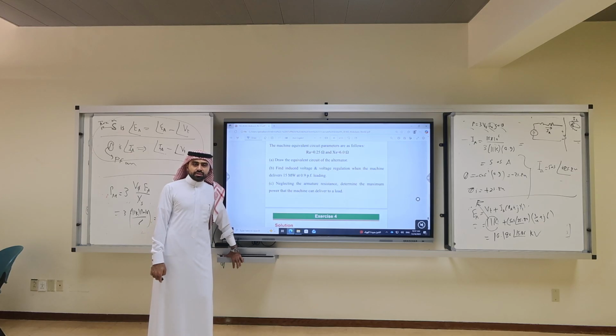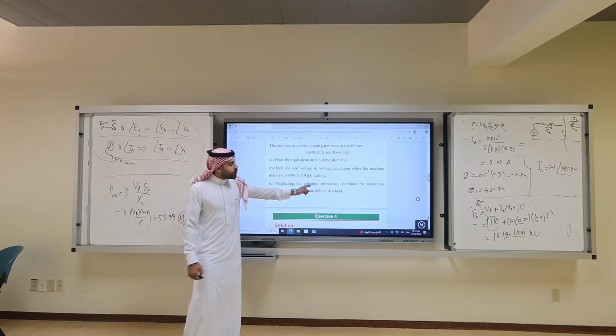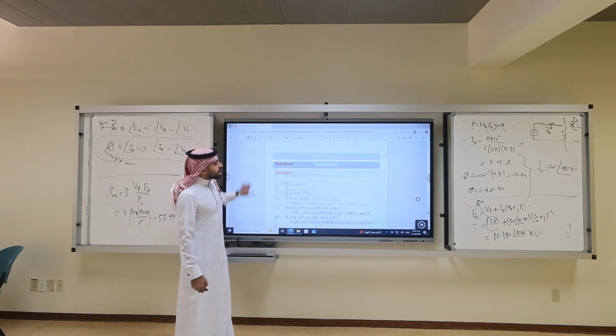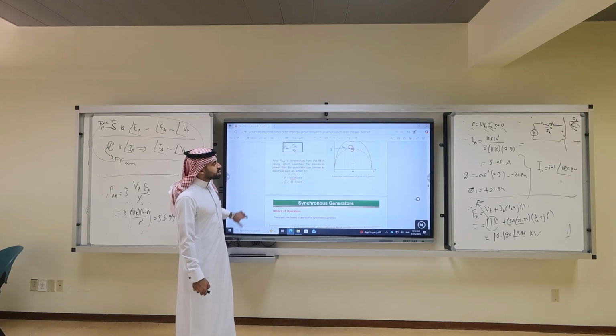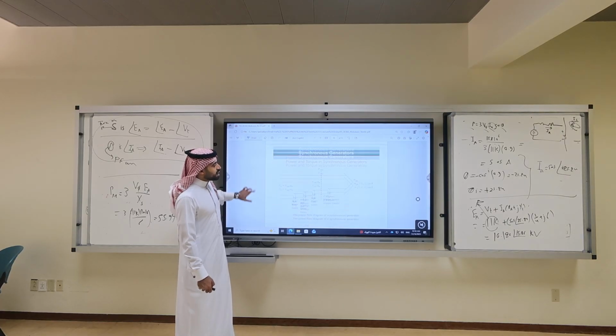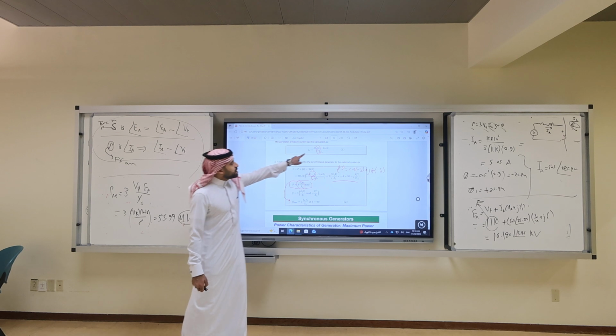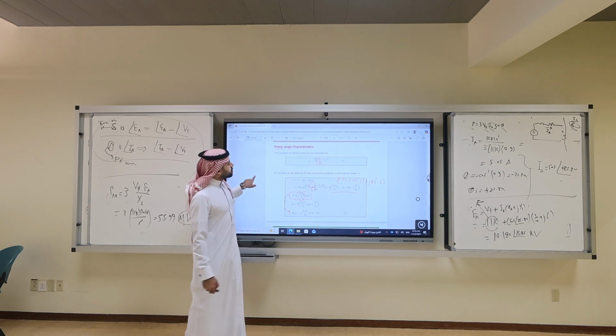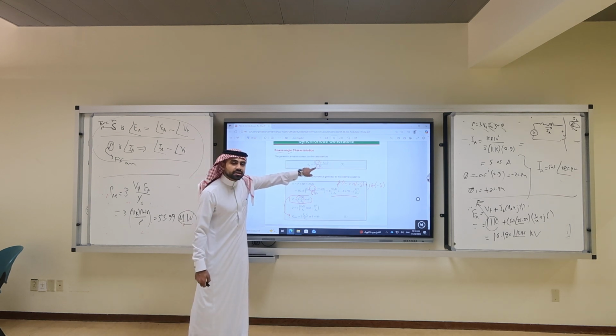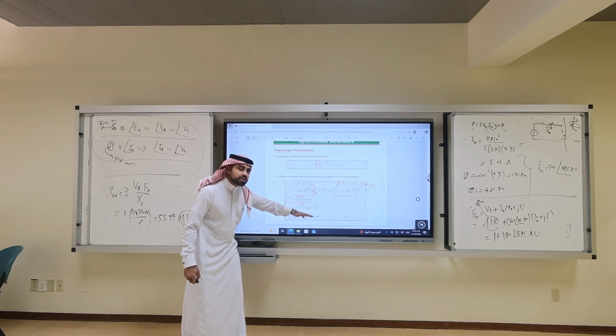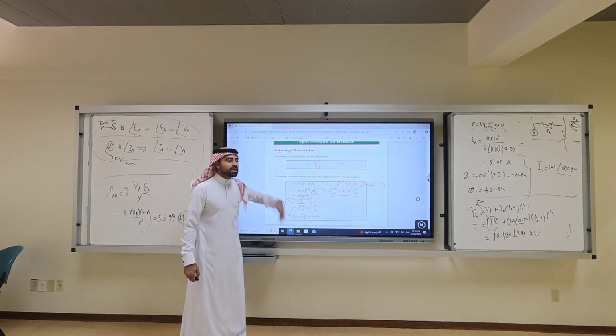Do you have any other questions? Yes, the homework is due today. Doctor, in part C, what changes when it says armature resistance? Because in the power equations we neglect RA. If you go back here, we didn't include the IA, we ignored the RS. We did all the calculations assuming RS is 0. If we include RS, it becomes more complicated.